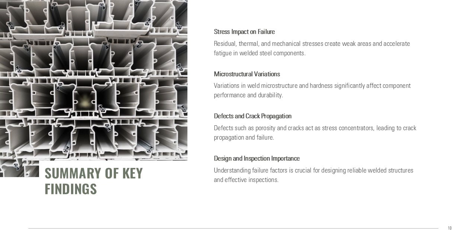Fracture mechanics principles explain crack propagation and failure modes. Weld characteristics such as microstructure and hardness influence performance, and defects like porosity and cracks act as stress concentrators. Understanding these factors is essential for designing reliable welded structures and implementing effective inspection protocols.